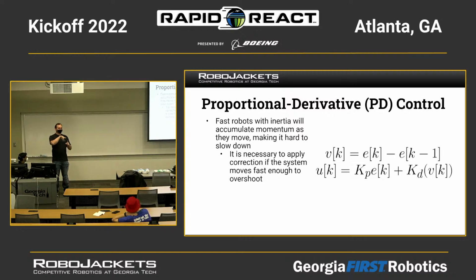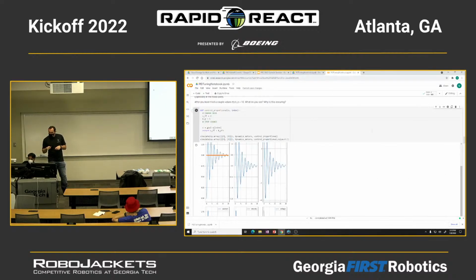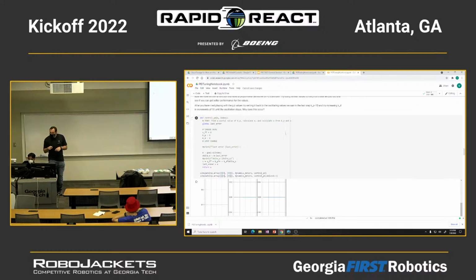So if I have a P controller, I'm going to start going up like this. My error is large, I move up like this. But since my error decreases over that time, I damp out using the D term. So if we go back to the notebook, let's go down. And then set P equal to 5. And then D is equal to 1, I guess.